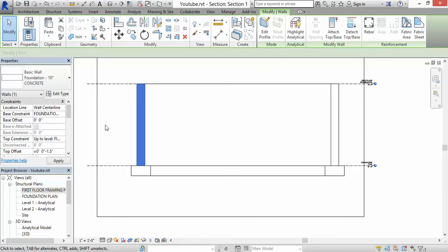Next, we're going to subtract the joist depth. The joist that I'm going to use is 2 by 10s, so minus 9.25 inches. And last but not least, I'm going to have some sheathing, and my sheathing is going to be 3/4 of an inch, so minus 3/4 of an inch.